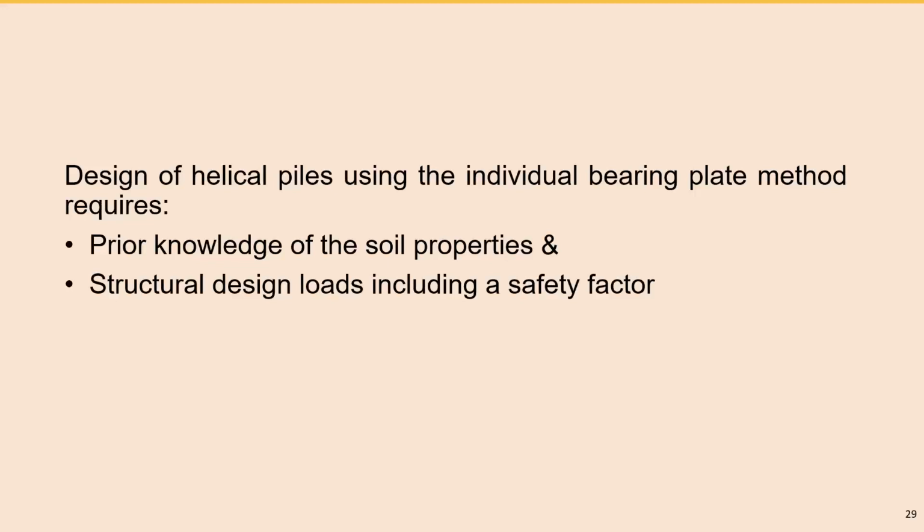There is also the Deep Foundations Institute, I worked on that too. They have a publication about design of helical piles. You can go to DFI and buy it. I believe it's $25 or $50, I don't know. But it's really a good document about general design of helical piles. They also use a safety factor of 2.